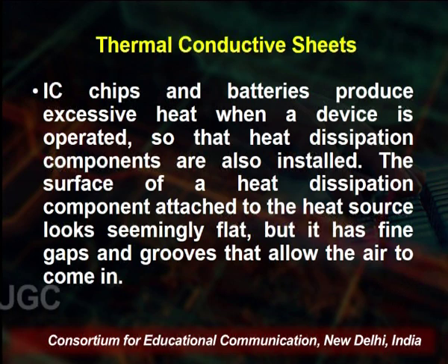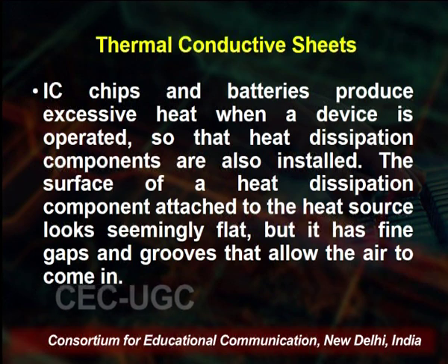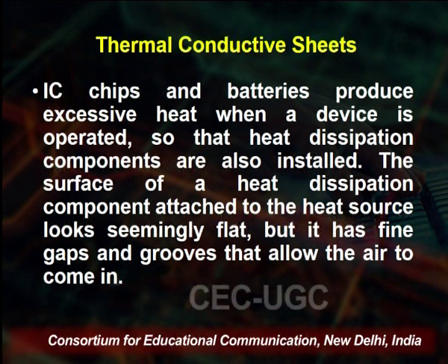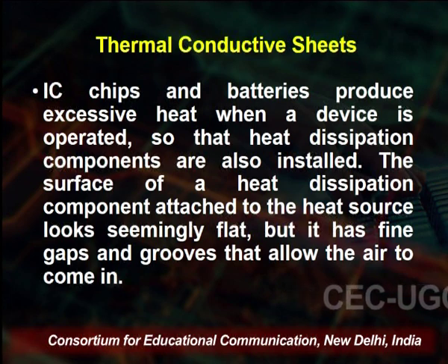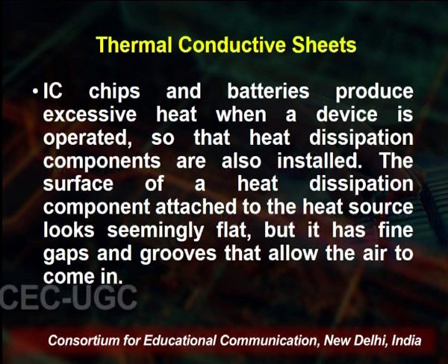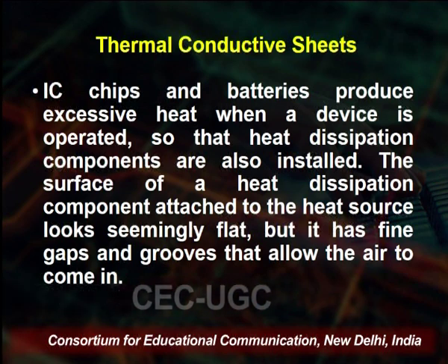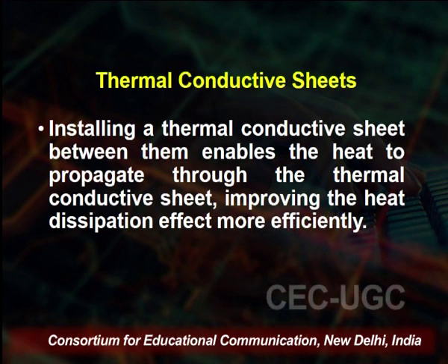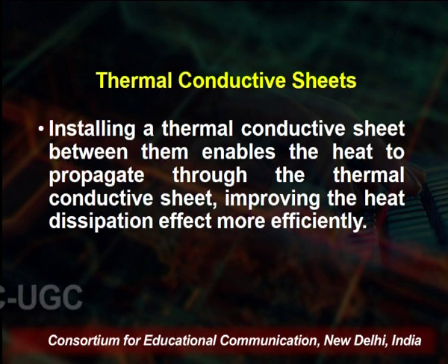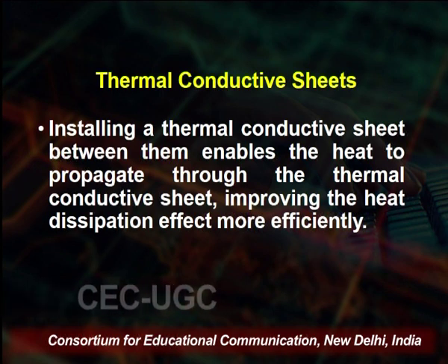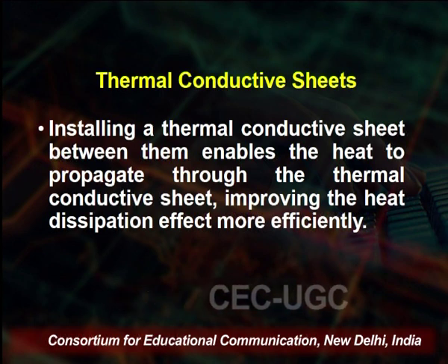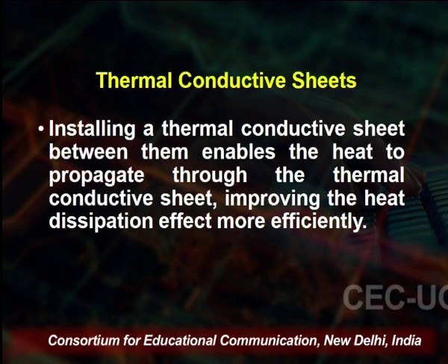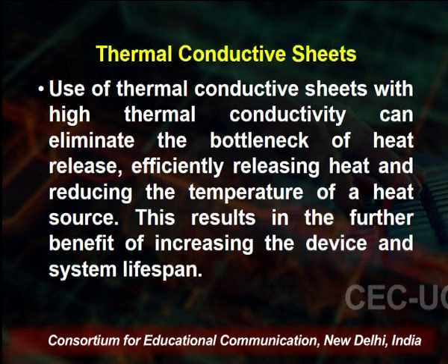The surface of the heat dissipation component attached to the heat source looks seemingly flat, but its fine gap grooves allow air to come in between. So installing a thermal conductive sheet between them enables the heat to propagate through the sheet, improving the heat dissipation effect more efficiently.